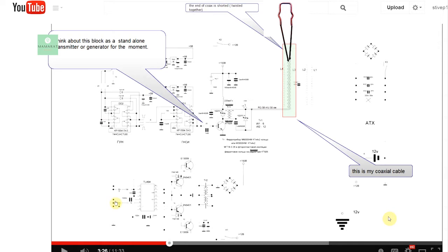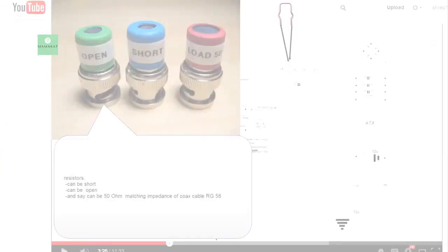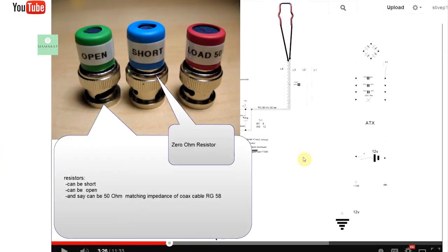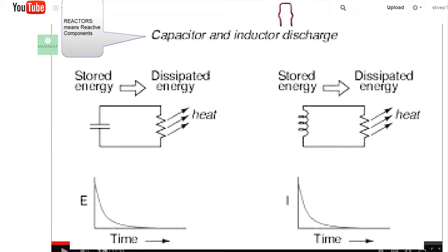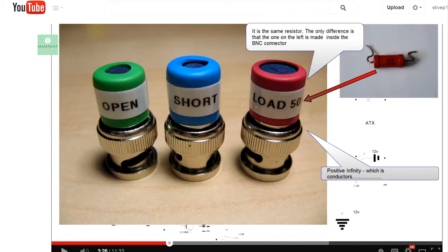of all the possible resistors you can put on the end, everything from a short circuit, let's call it 0 ohms, up to a complete open circuit, it's called infinity. So you get a whole continuous range of resistors, from short to open. And you also have a whole continuous range of reactors you can put up there. Everything from negative infinity, which is capacitive, to positive infinity, which is inductive. All of those are possible. Okay, let's just talk about resistors at first.